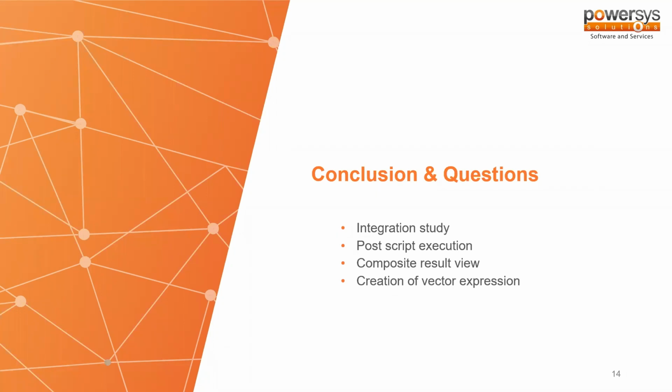Maybe before answering this question, I will mention that right now we don't recommend RT to be the source of the creation of the efficiency map, since we introduced efficiency map studies about two or three versions ago. This should be the place where you create efficiency maps. RT was the tool in the past, but now please use efficiency map studies.